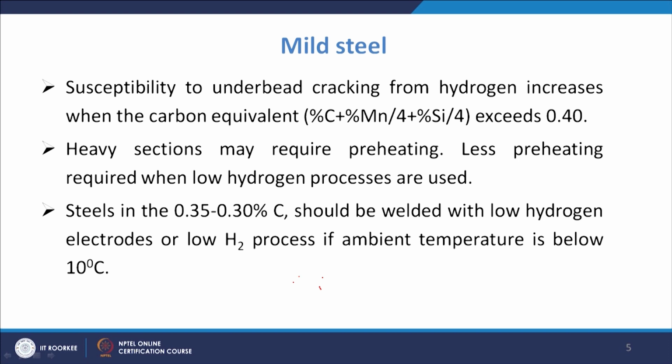So, in those cases you do not have so much requirement for preheating. That depends upon the low hydrogen processes or low hydrogen electrodes which you use. In that case the extent to which you have to do the preheating may be affected.